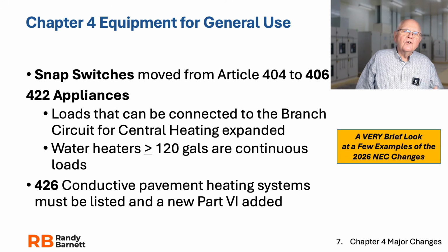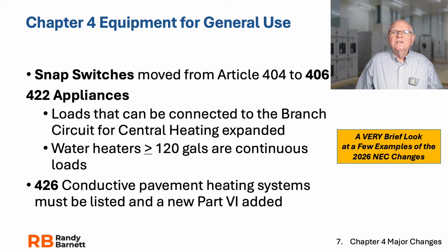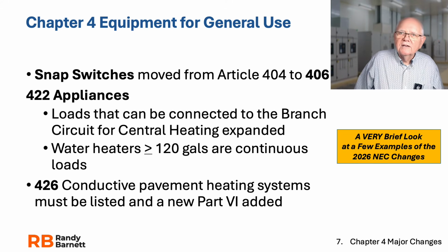Take a look at Chapter 4 now. Chapter 4, Equipment for General Use. What are some of the changes we see? Snap switches, okay, our light switches on the wall, have been moved from Article 404 to 406. Why would they do that? Because they belonged in 406. I don't know why they were in 404, whatever. But now Article 404 is for our general use switches.